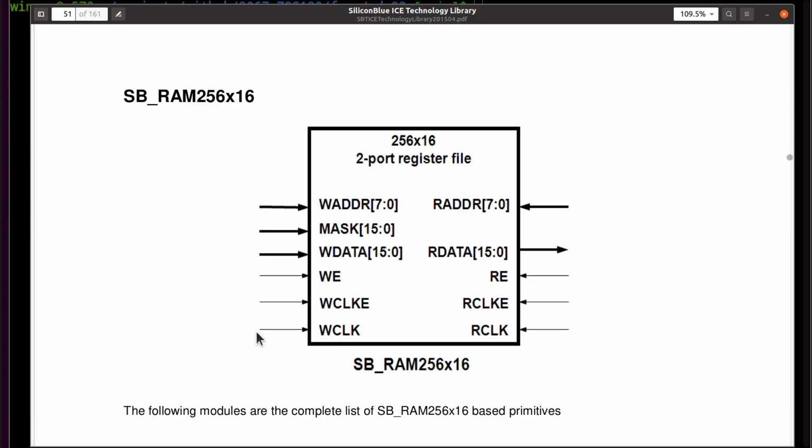Right now, we don't care so much about the separate clocks because this is all in one clock domain, and we'll see in a minute that this whole thing exists in the VDP part of the design that we're going to look at. And the write side of these are going to become part of the actual memory blocks that the FPGA has, but we're going to use an inferred memory to create it.